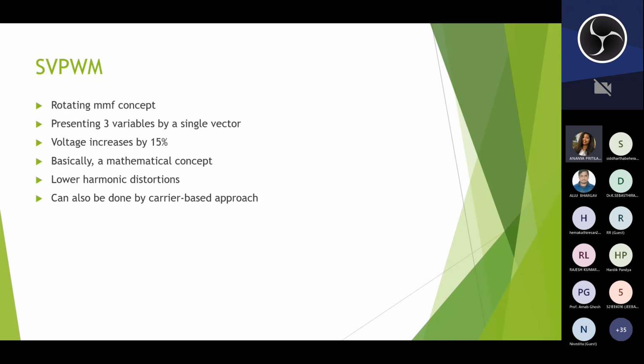Space vector modulation has now become a standard for switching power converters, as all of us already know. SVPWM is said to be a better technique for PWM generation in terms of better utilization of DC bus power, efficient switching, and minimum current ripples, which causes the total harmonic distortion to be low.